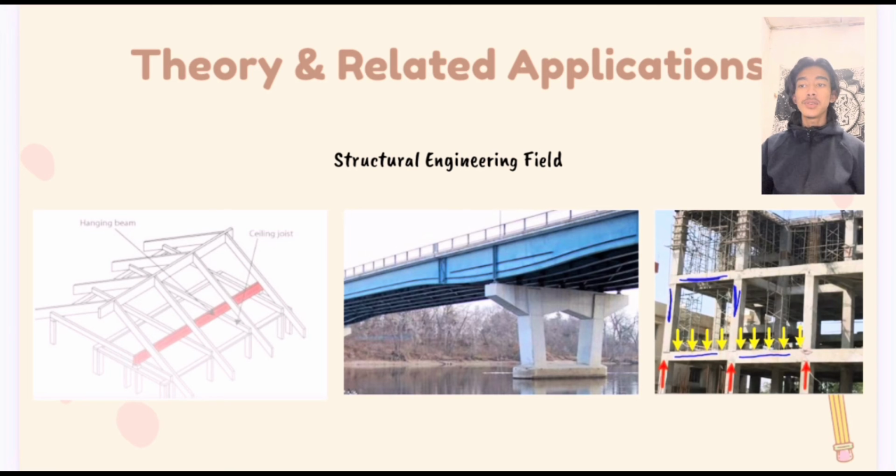Failure can occur due to bending when the tensile stress exerted by a force is equivalent to or greater than the ultimate strength of the element. However, although the mechanisms are different, a beam may fail due to shear force before failure in bending. If a beam is not well restrained, a bending force may cause it to rotate about a pivot point.